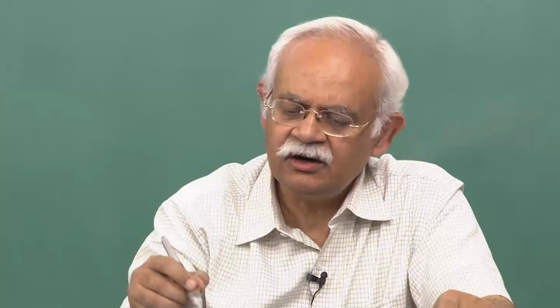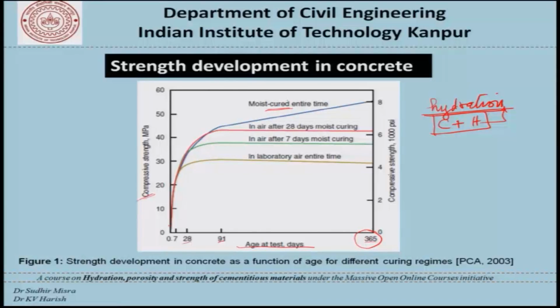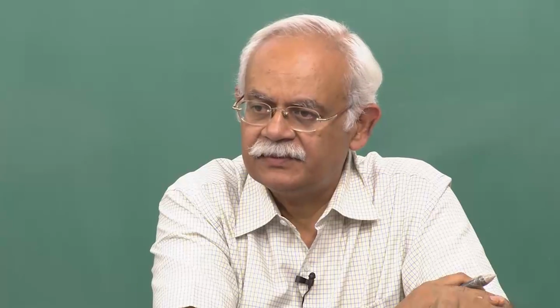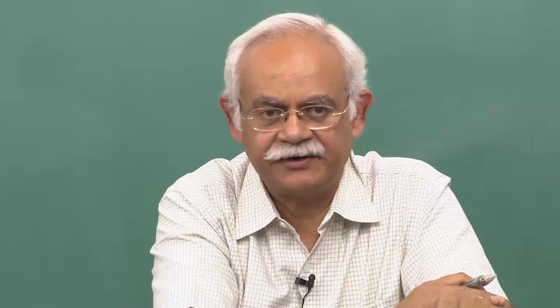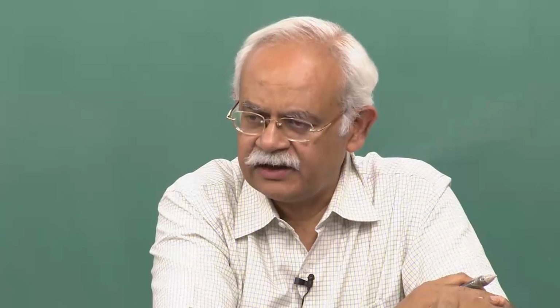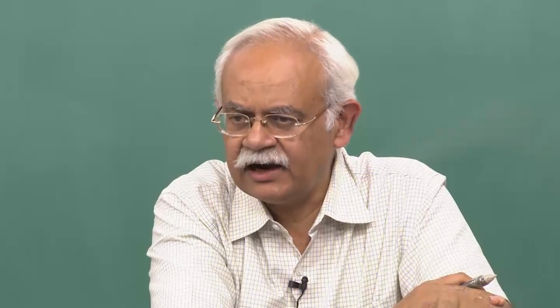So, now what promotes hydration is something called curing. Even though we are not talking about curing today, we will spend some time talking about curing, its importance and the different methods that we have. But the fact of it remains that curing is a process by which we try to provide conducive environment to cement particles so that they can continue to hydrate. Hydration is a slow process to that extent and continues over a long period of time.